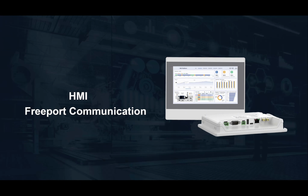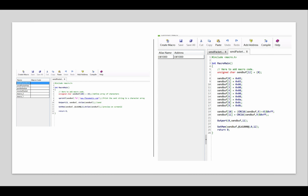Unlike pre-configured industrial protocols, e.g., Modbus, Profibus, Freeport does not enforce a specific data structure. Instead, it empowers developers to design their own communication logic by directly controlling the serial port's transmit and receive operations.